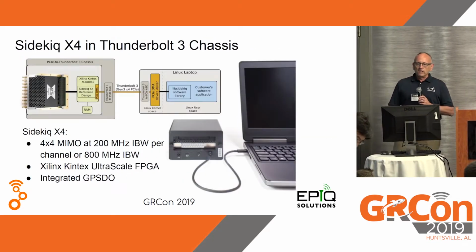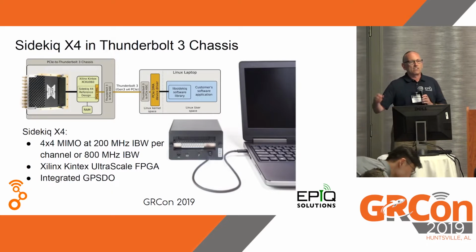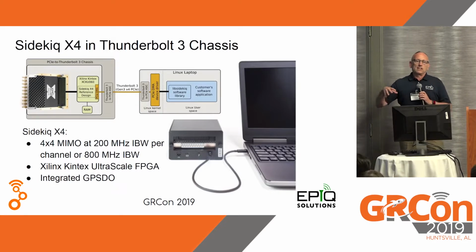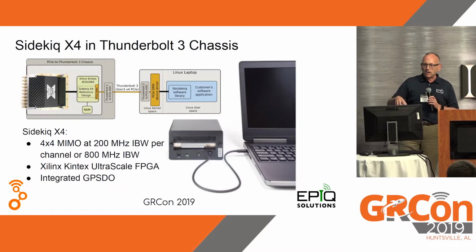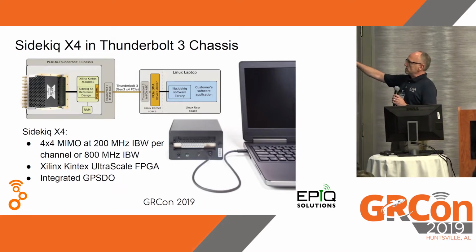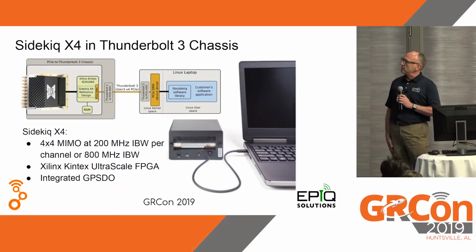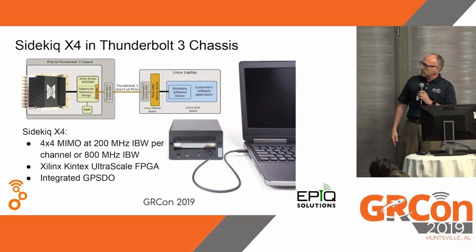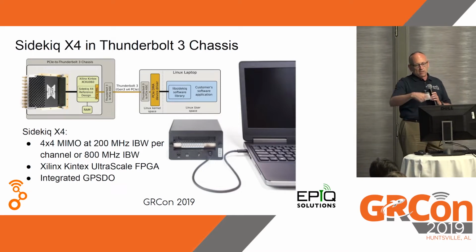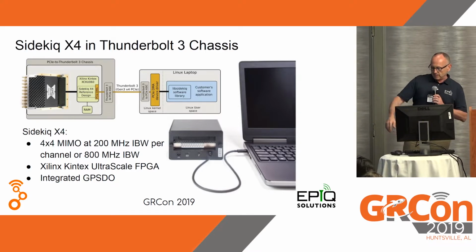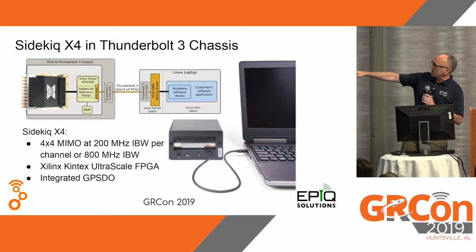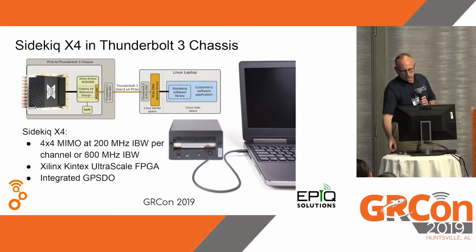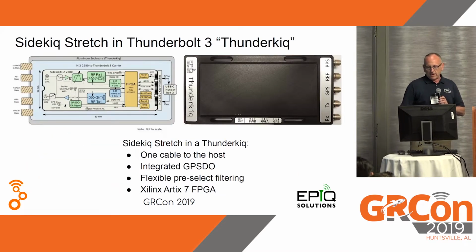So a couple of real-life examples. We have a couple of SDRs that we already use Thunderbolt 3 on, one being our X4 system that gives you a capability of 100 megahertz IBW. It also gives you capability of 4x4 MIMO, and as you can see in the picture, we connect it up, when it's installed in this platform, right to our host with that one cable.